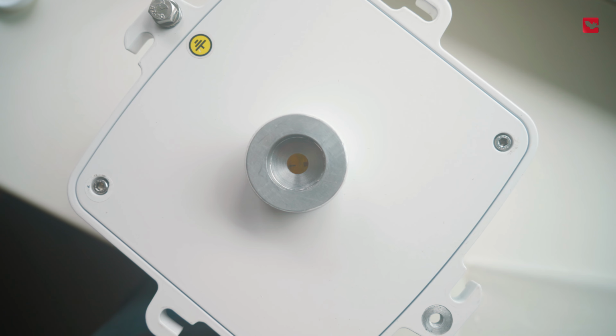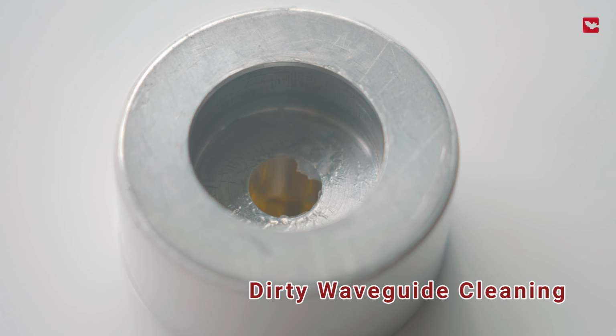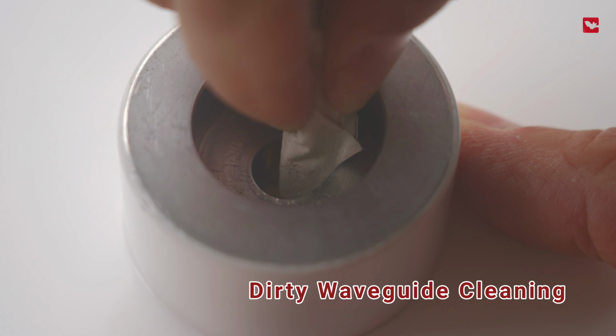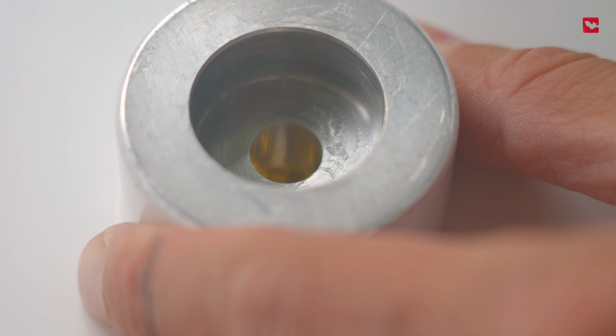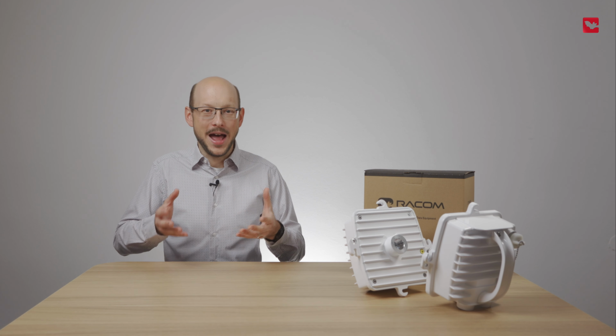In case this does not help, you should inspect the waveguide to check it's clear. Check the antenna frequency or any damage to the unit, waveguide or the antenna. Since our match, we know we don't have to.